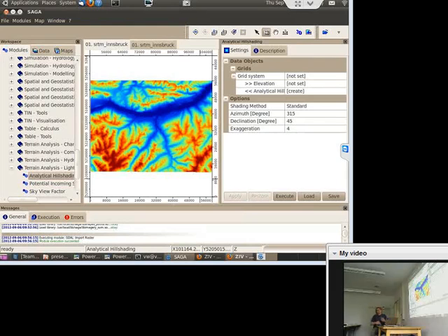And as I said, you will not be able to compute on grids which are in different grid systems. The first thing is that you have to select a grid system. So in our case, we only have a single grid system selected. And once you have specified the grid system and you click into the elevation data set parameter, you will get all data sets listed in this grid system. So we can select our SRTM dataset. Yeah, and then we have an output dataset which will be created. We could also overwrite an existing dataset, but in our case, we like to create a new one.